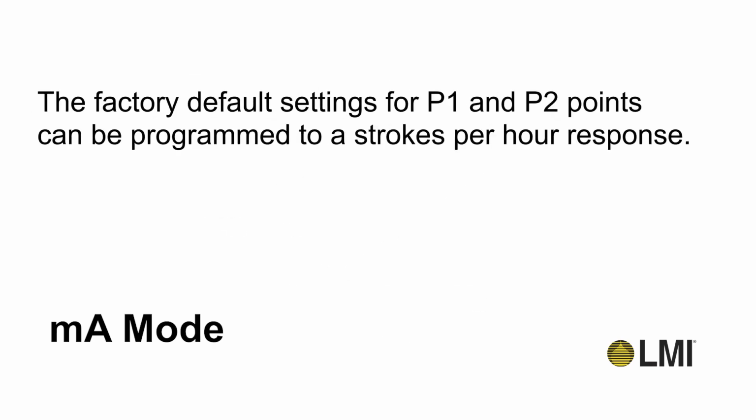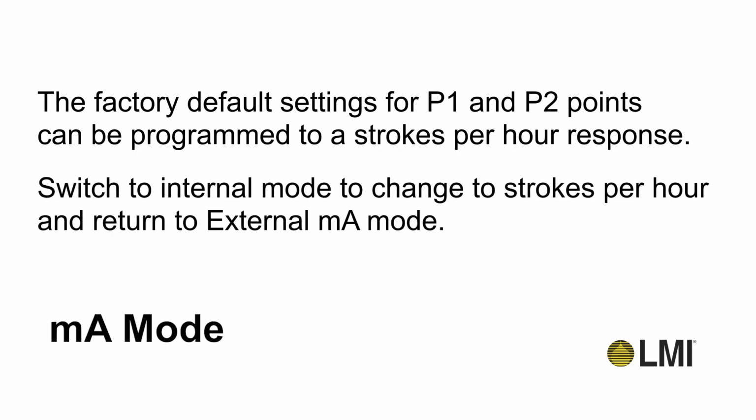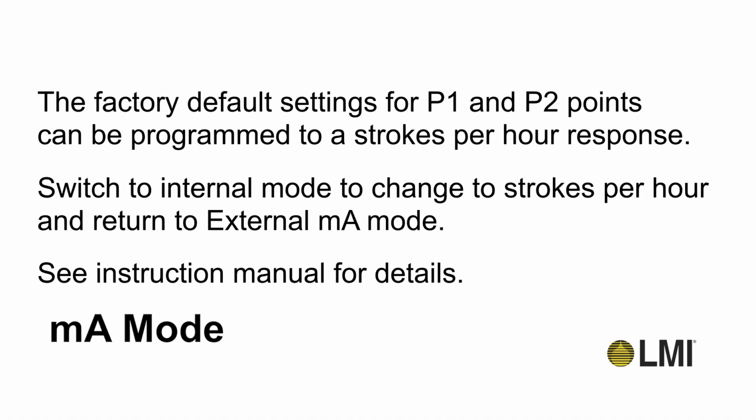The factory default settings for P1 and P2 points can be programmed to a strokes per hour response. Switch to internal mode to change to strokes per hour and return to external milliamps mode. See instruction manual for details.